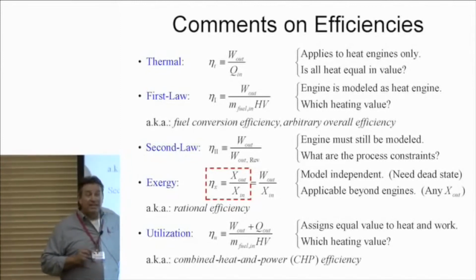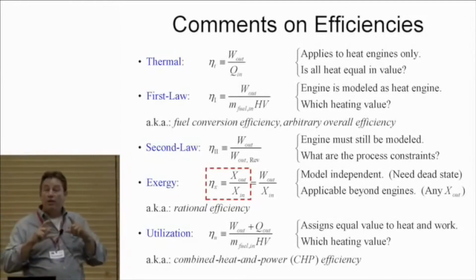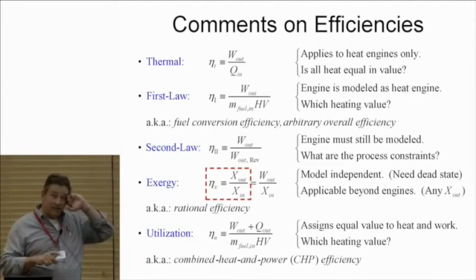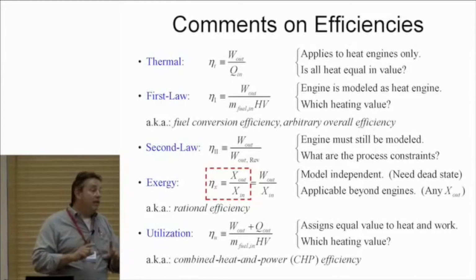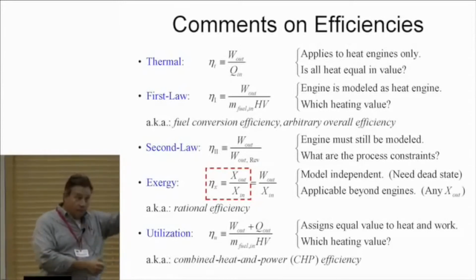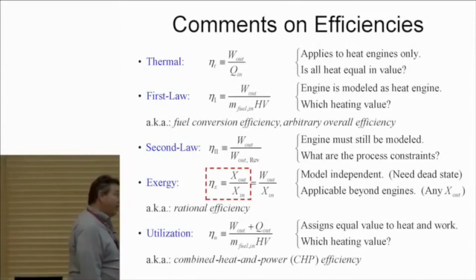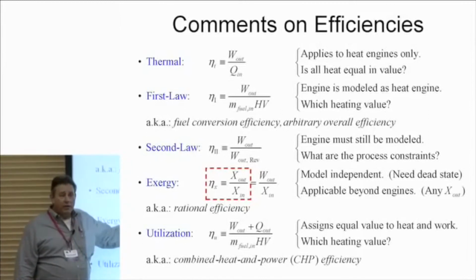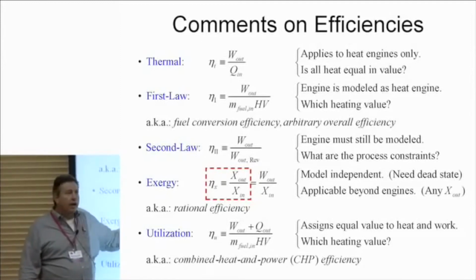But we have something that at least is clean because we're asking for how much work we could theoretically get from the resource in the local surroundings. Tells us nothing about how we'll actually get it, but now we at least have a yardstick. And that's the key thing about Exergy. It's an unambiguous yardstick that you hold up next to your system all the time as you go. And not just a matter of engines, it could be whatever transformation you're doing. I could be making hydrogen from methane or from coal. This is what I put in, that's what I got out, that's how I evaluate.